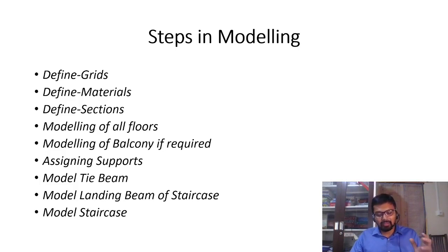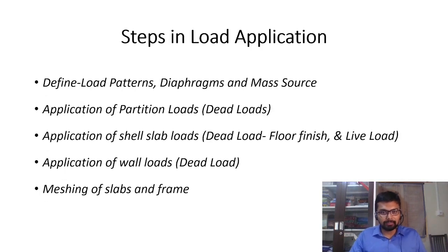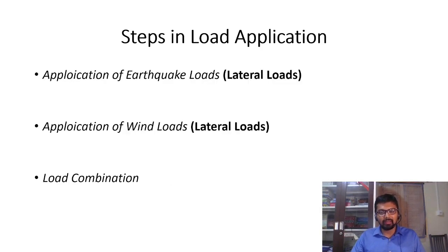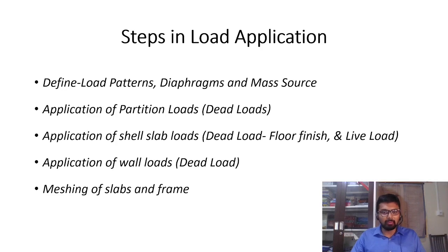And if you want to provide just a UDL, we can do that, or else you can model the staircase. So you have two options: either you can model the staircase, or you can just provide the load of the staircase on the landing beam. Whichever is easier for you, you can do that. Then you have to define load patterns, diaphragms, and mass source, which is very important. These are the parts of the load application, and meshing of the slab is also very important here.